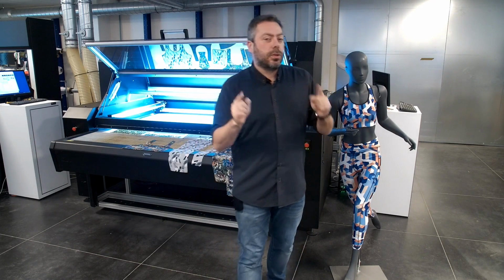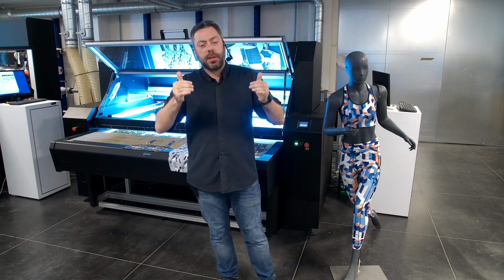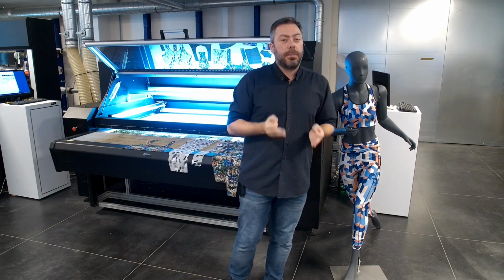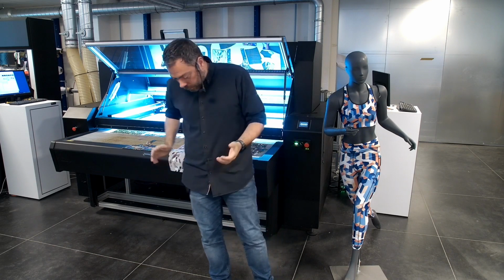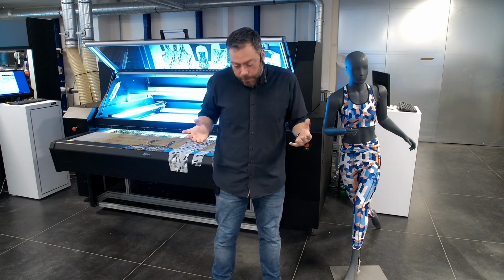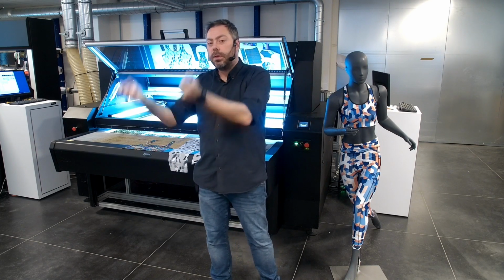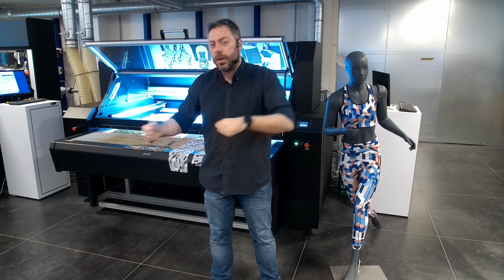One of the things that you should have noticed is that while the media is being transported, the material is already being cut. This is basically also one of the benefits of laser cutting. If you cut with a knife, you're generally pushing on your fabric, and you're going to move around your fabric. If you're transporting your fabric, there's no chance of, let's say, holding down your textile. There's no chance of creating a vacuum, because you need to move your material, vacuum it down, and then start to cut.